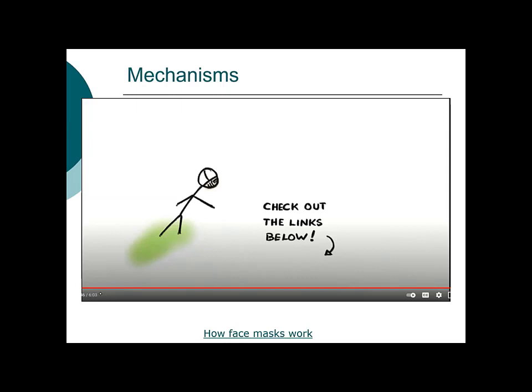commercial industrial systems. It's not breathing, but it's the pressure drop. And it's really the pressure drop across that fabric that makes it difficult to breathe. So if that fabric is too tight, then you've got a very large pressure drop across that filter, and therefore it is difficult to breathe. Same thing is true in these industrial systems, except they're not breathing, but the greater the pressure drop, the more energy you need to supply in order to get that gas to flow across that filter material.